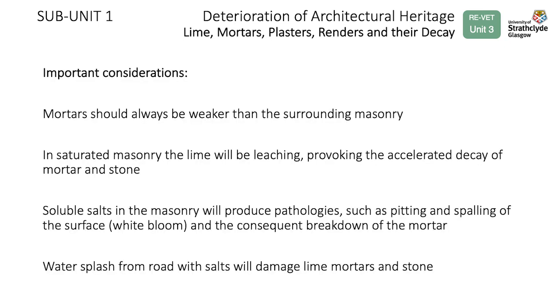Some important considerations are that the mortar should always be weaker than the surrounding masonry. In saturated masonry, the lime will be leaching, provoking the accelerated decay of mortars and stone. Soluble salts in the masonry will produce pathologies such as pitting and spoiling of the surface, white bloom, and the consequent breakdown of the mortar. Water splash from roads with salts will also damage lime mortars and stone.